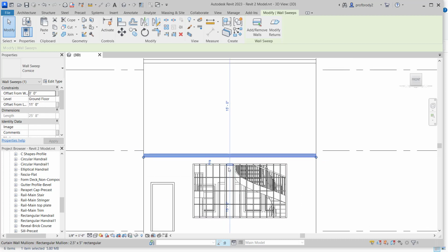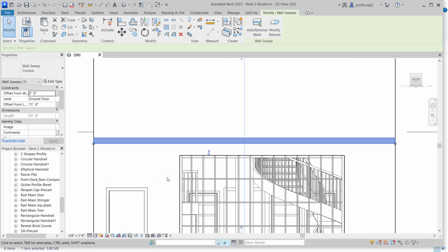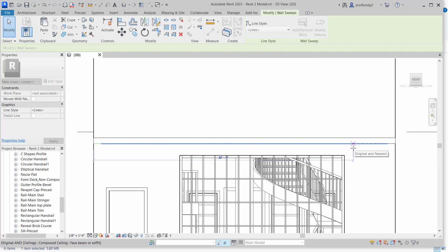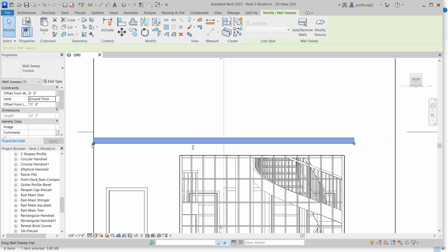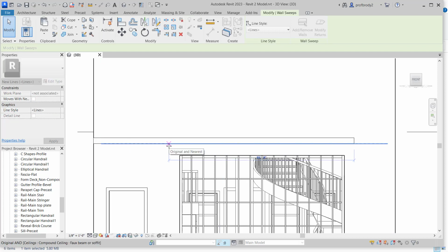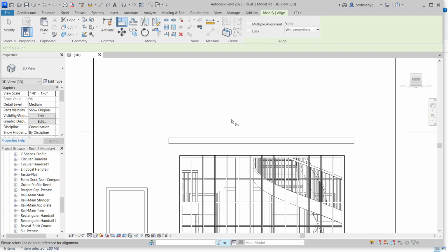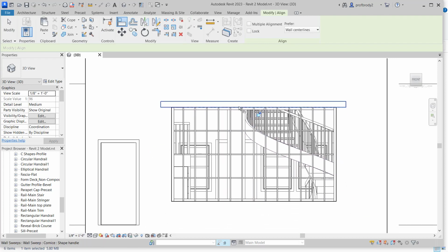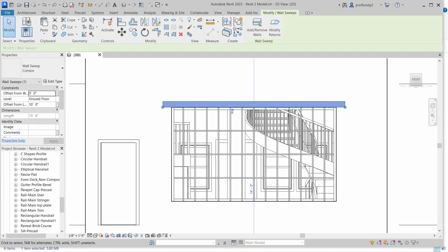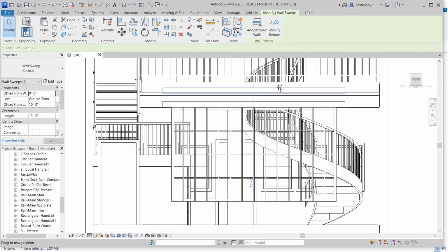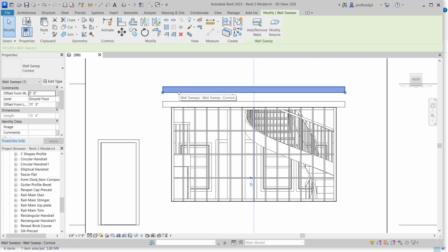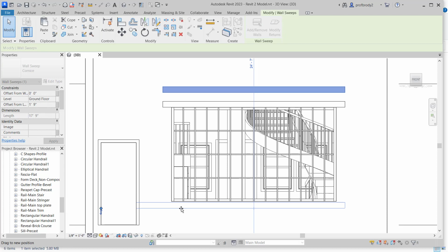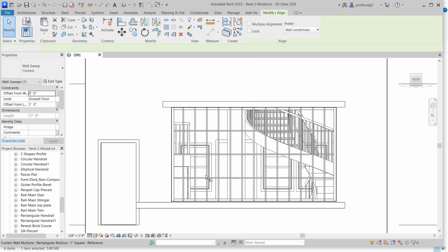Anyway, so if I wanted to create, say, the lintel over this window, I could just drag this down. I can even shorten the object here, or I can use the Align tool to force it to snap to the top of the window. And there you go. I could even lock it in position as we've seen before. And I can copy this guy and maybe make it a windowsill here.